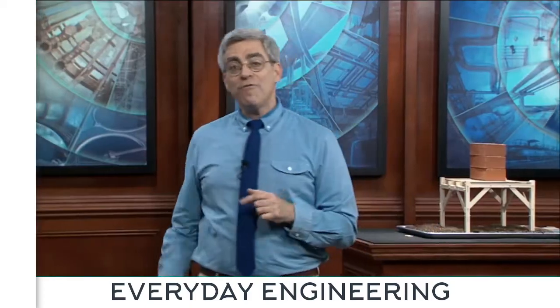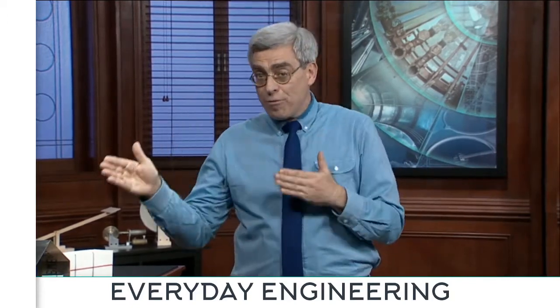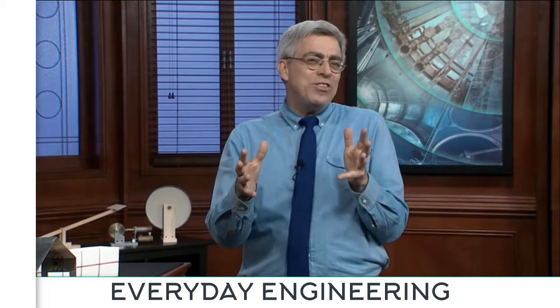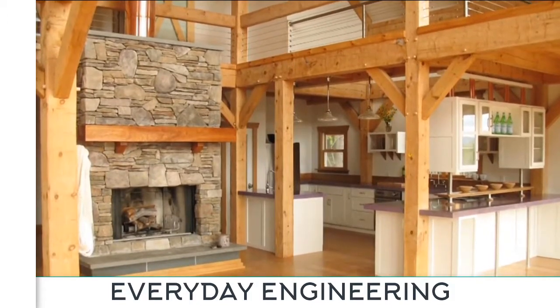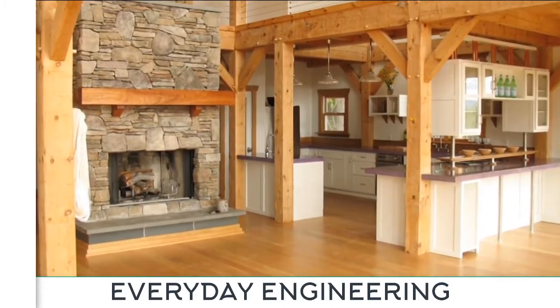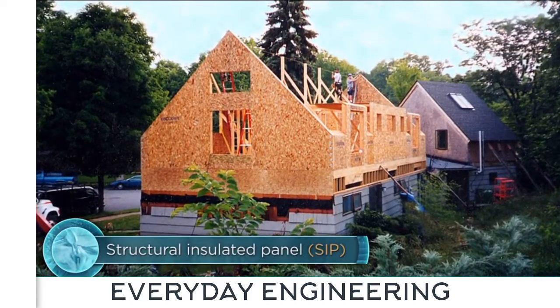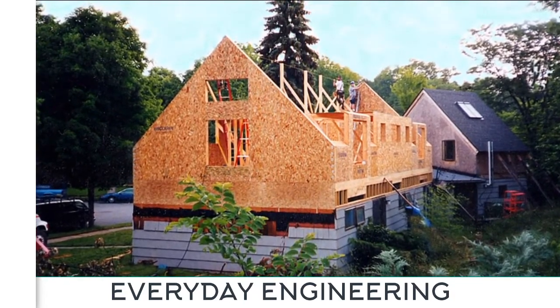For now, we should recognize that the dominance of the platform frame in modern residential construction does not render the other two structural systems irrelevant or obsolete. Both bearing wall construction and heavy timber framing have retained a significant presence in residential construction and, indeed, have actually been staging a bit of a comeback in recent years. For example, heavy timber framing is becoming increasingly popular for high-style homes like this one, because its aesthetic qualities evoke a certain rustic charm. A recently developed bearing wall technology called the structural insulated panel is becoming increasingly popular for highly energy-efficient buildings, as we'll learn in our later lectures on energy efficiency.